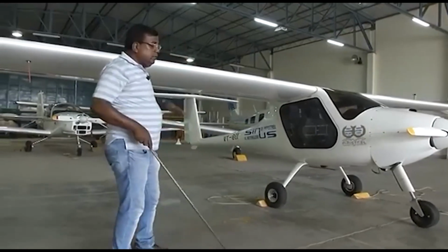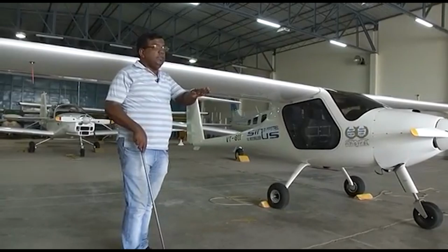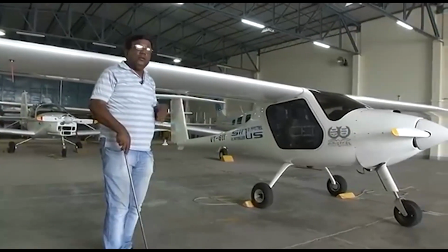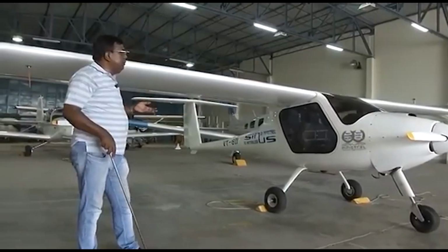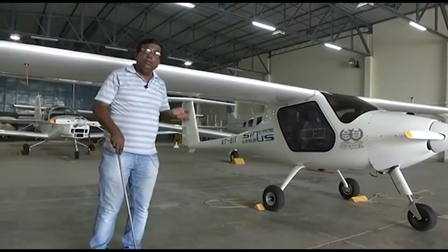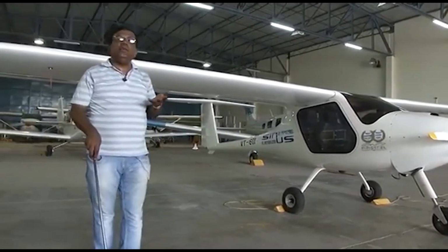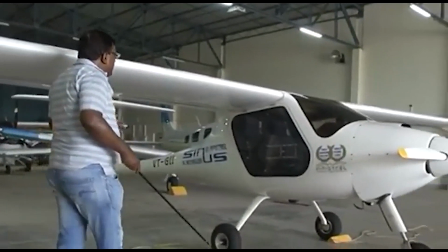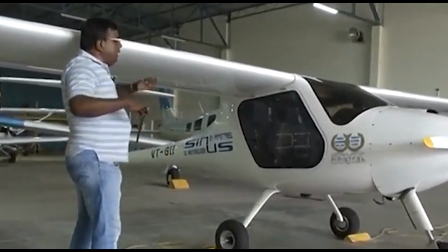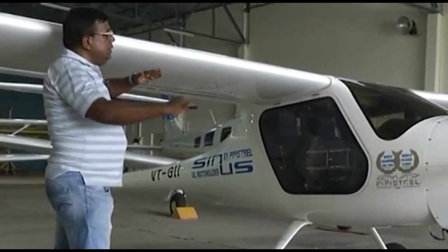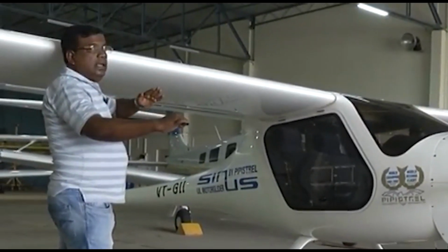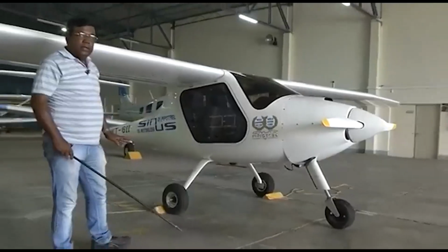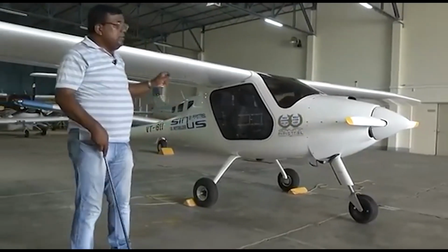Why all these things? Why do I try to lift the nose up? Because I want to get lift. Because for takeoff, I need to have lift a little more than the weight, or at least lift equal to weight. Okay? Now, for getting that lift, I need an angle between the airplane and the velocity vector. That is why I have to roll this airplane for a tricycle landing gear configuration. Okay? This is one part.